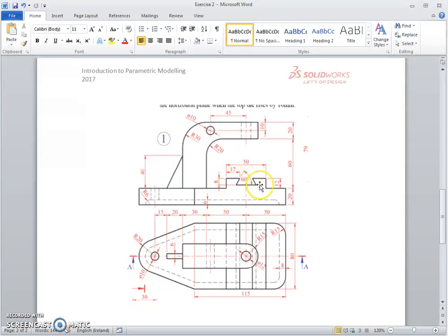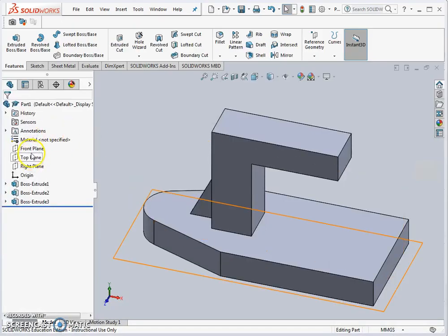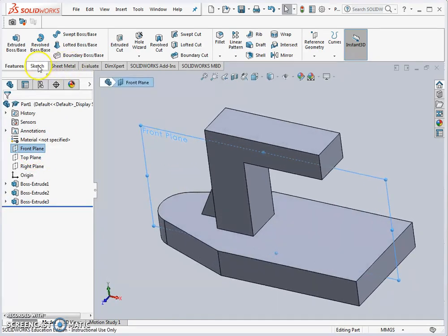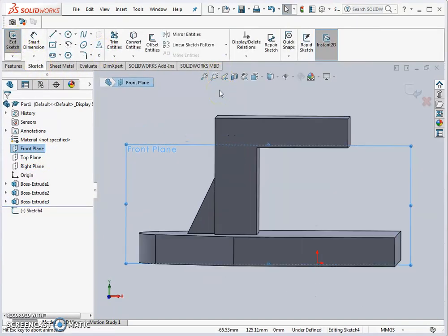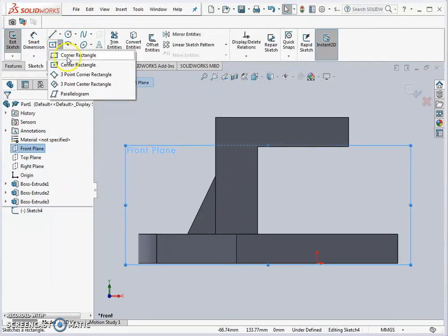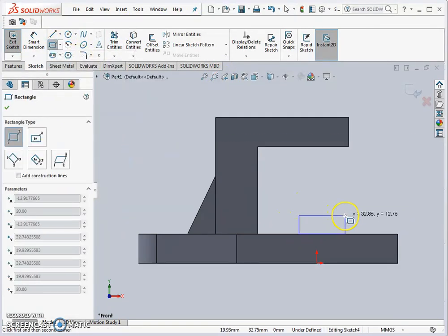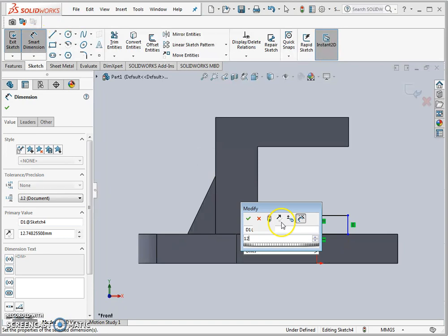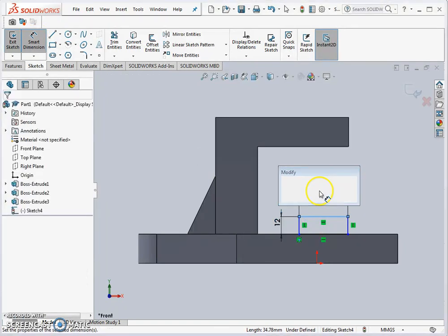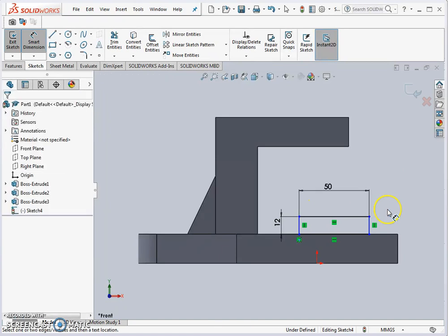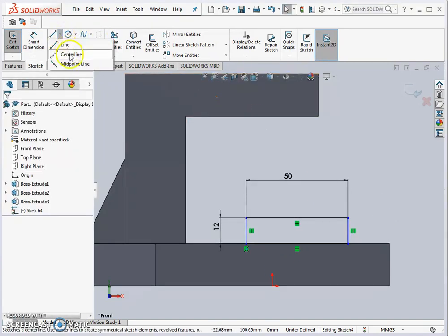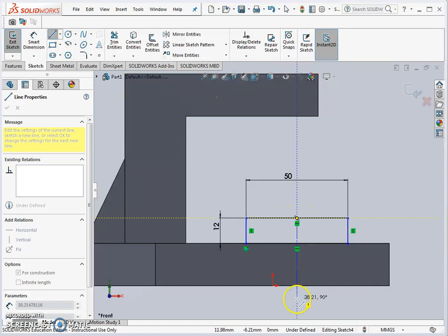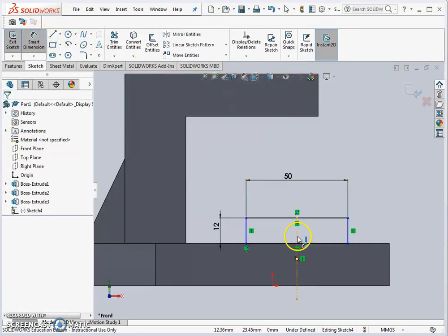So the next feature we're going to look at here is the dovetail groove on the component. Again, it's on the center plane, and we look straight in at it. We're going to sketch a full rectangle first, snapping on the top surface. In addition, we're going to draw a center line and dimension the distance out from the center line to the edge.